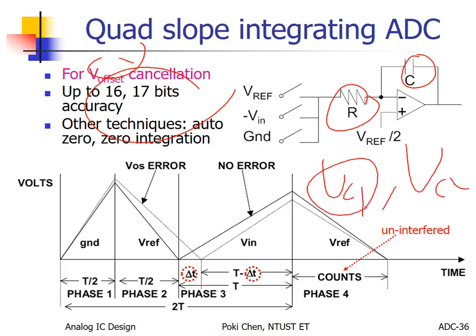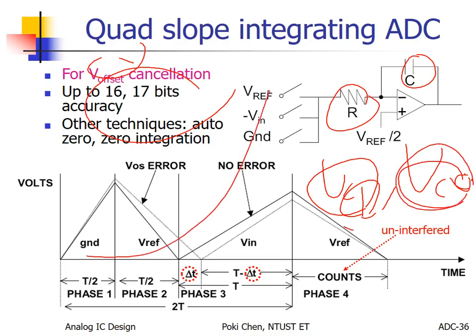VC1 maybe is not so harmful, but VC2 is really harmful, because what is VC2? Voltage coefficient. This is for first order, for second order. First order, according to linearity, I think it's not harmful. But second order means you will have some kind of curvature, right? It will harm the charging and discharging. It will never be a linear one. It will be some kind of curvature.